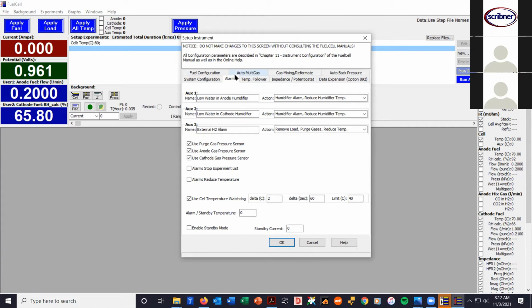It's not a good thing to try and heat an empty tank, because there's a big thermal disconnect between the temperature probe, which is in the humidifier and typically is in water, and the heaters themselves, which are on the outside of the tank. If there's no water in the tank, it takes a long time for the heat that's put into the stainless steel tank to actually end up being registered at a thermocouple, which would be in air, or gas at least, if the tank is empty.